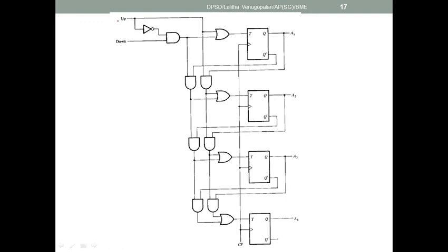So this up one has got an inverter connected to it, and then this would be used to toggle between the inputs. So suppose if you want an up counter, then you just use the up signal and OR it with whatever is the output of your down. So one has to be high and one has to be low, and then this AND gate would give you the output accordingly. And then you can use this combination of logics to feed your input to your T flip-flop and then get your up or down counter.